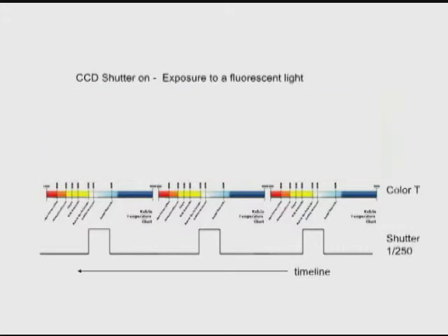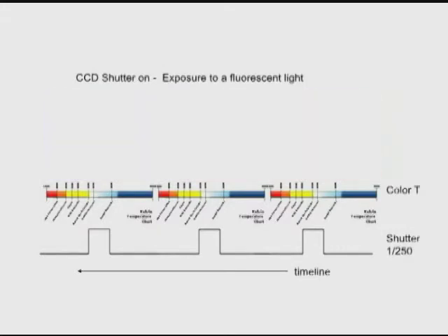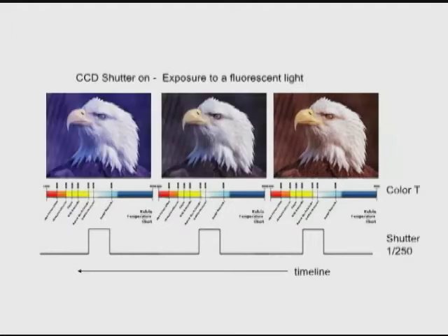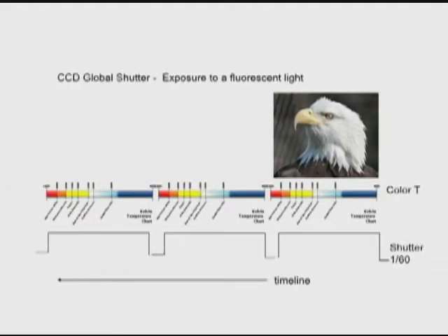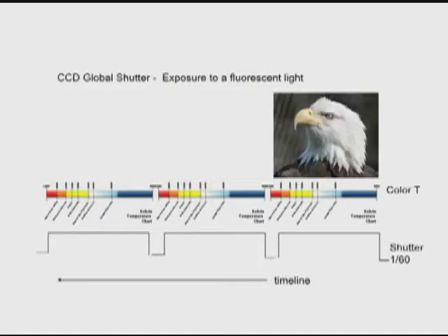So you want to stay away from a shutter mode if you are in a fluorescent light and using a CCD camera. This next picture shows that if you use your shutter correctly at 1/60th, you will not face this problem. In the next session, we will explore what vertical smear is and how CMOS come into play in the camera.